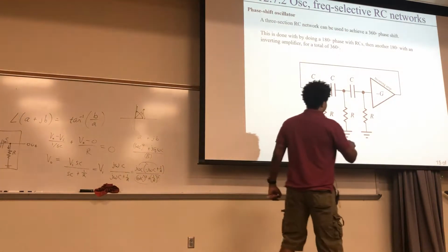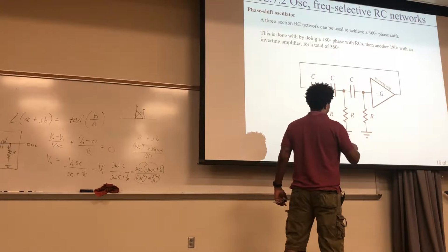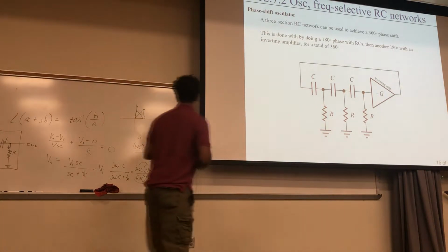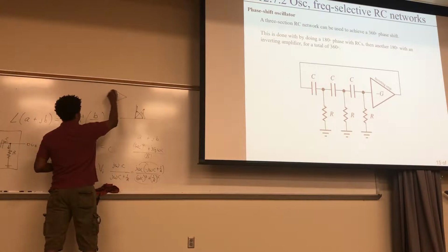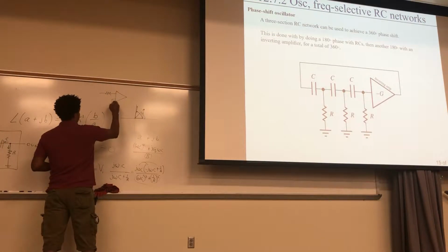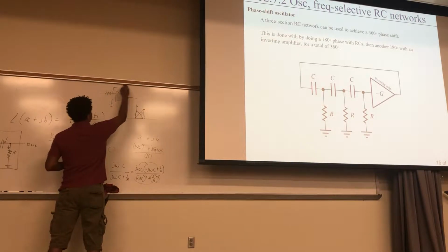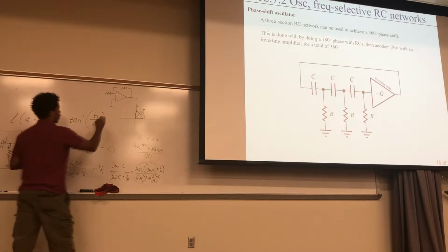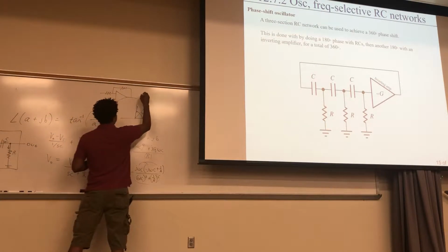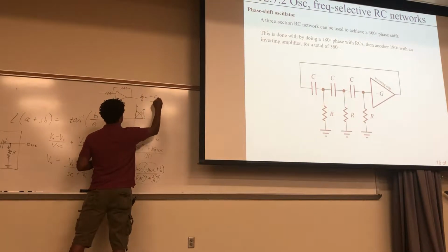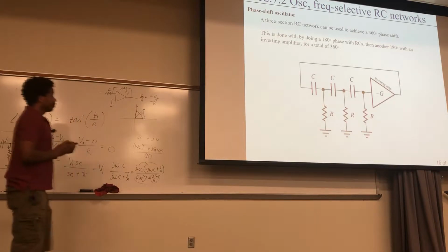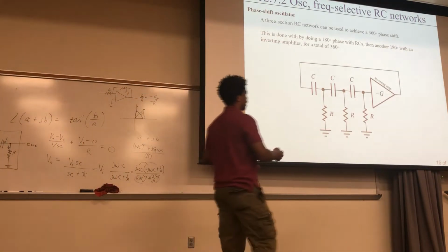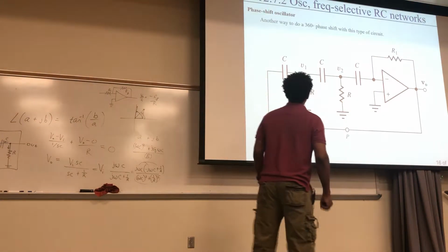And this symbol, so this is the first time I've seen the book just use this all by itself. But what they're doing here is a lazy way of making this type of amplifier. Okay, where your V out over V in is negative R feedback over R1, and this is your R feedback, and that's R1 right there. Okay, but they just do it like that.